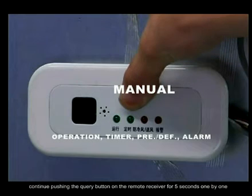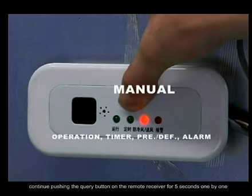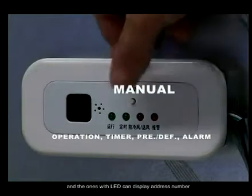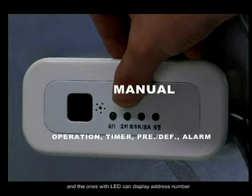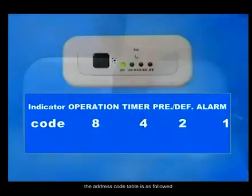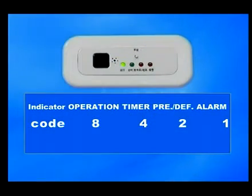Continue pushing the query button on the remote receiver for 5 seconds, one by one. The indoor unit will display the address, and the ones with LED can display the address number. The ones without LED can be calculated according to the lighted lamps. The address code table is as follows.